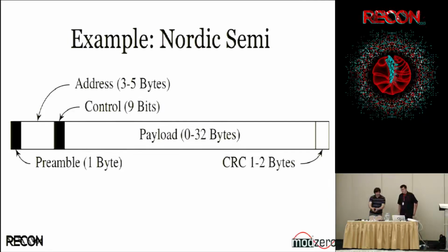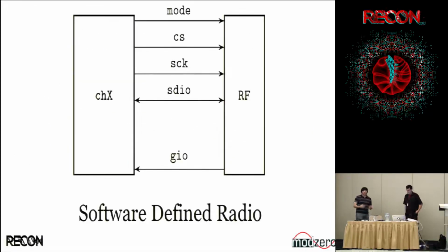But basically, with the Datenkrake running at 50 megahertz, this is not a challenge at all. Once you've captured one of these packets, once you've matched the preamble, you can test the rest of the data, try the CRC out for any bit length, just assuming that the data you've gotten is correct, and ensure that you actually decode a valid packet. And so now you're no longer seeing noise. You see only data that's actually been decoded by the hardware, where the CRC check passed, where you matched the preamble, and you're not second guessing yourself.